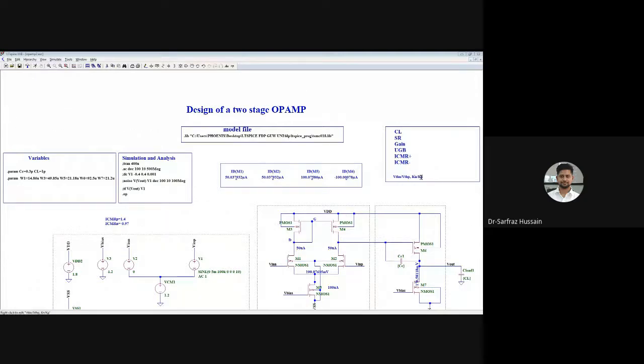Okay, so this Kn and Kp and Vthn and Vthp, we can find out from the Vt0. So from that Vt0 we can take, and if we are considering the Vthn max, then we'll add 10% to that. And if we are considering the minimum value, then we will subtract 10% from the Vt0 value. So this is how we can find out the Kn and Kp value.